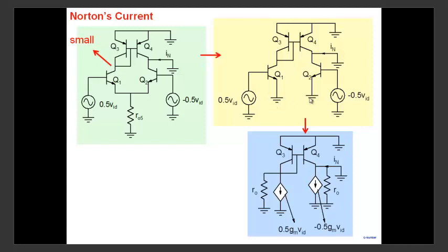Fine. If I do that small signal ground, then what happens is R05 disappears. Fine. We get this here. But still, the two circuits don't separate out because note that these two are still coupled together, Q3 and Q4. Unlike in the previous case where we had a left half of the circuit, right half of the circuit, and it was straightforward. They're still coupled together. All right. So let's see how to proceed with this.